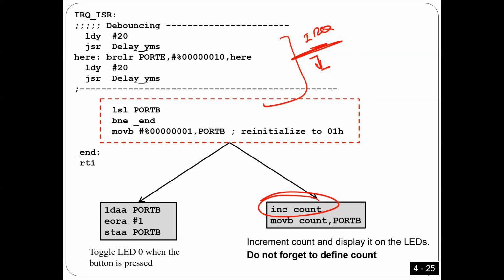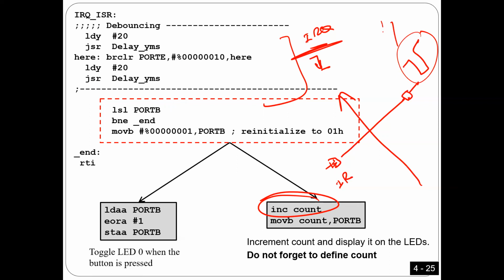There is one way, if I want to count, for example, the number of cars driving over the road, or the number of people who enter the store. The way we usually do it is we put here an infrared transmitter, and we have here an infrared receiver. You cannot see this light. So every time you enter a store, you are going to cut this line. Once you cut this line, you are going to generate a pulse this way. So if this pulse goes to IRQ, that means one customer entered the store.